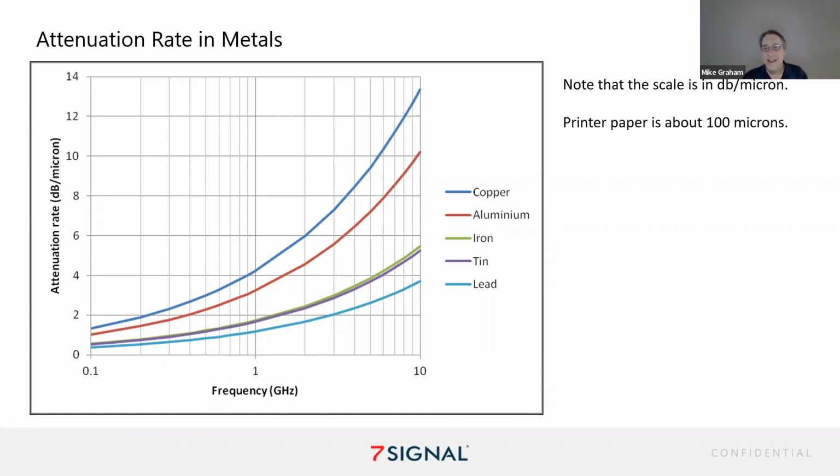As a quick test, I ran down to the store on the corner, grabbed a roll of aluminum foil, wrapped up all my equipment in it and retested. And it pretty much shut it down. We ended up going with metal enclosures and putting traps on everything and bandpass filters. But it makes a big difference if it's conductive.